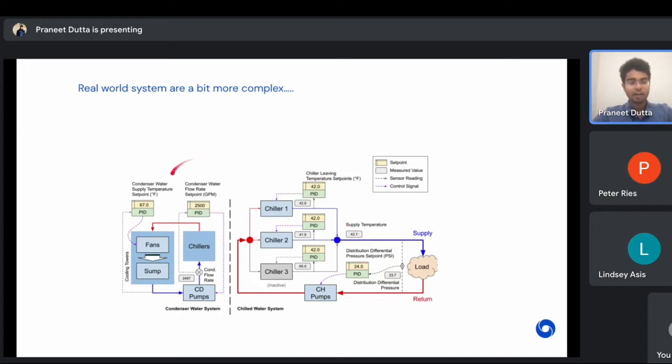We can talk about the flow rate of water on the condenser side. How fast do we want the water to be moving? And then how fast do we want the cooling tower fan to be moving? So we control the temperature based on how fast the fan can move. So these are all control mechanics that, before we got these artificial intelligence techniques involved, were written by algorithms, and they figure out what the optimal value for these are. Any questions on this?